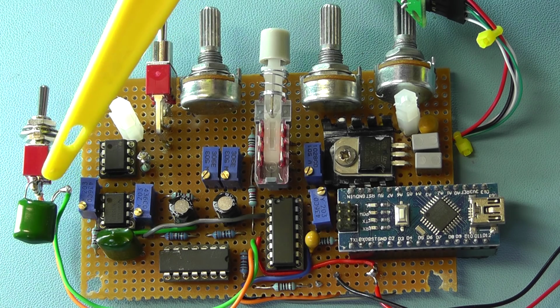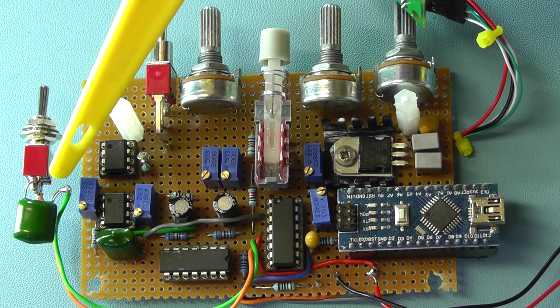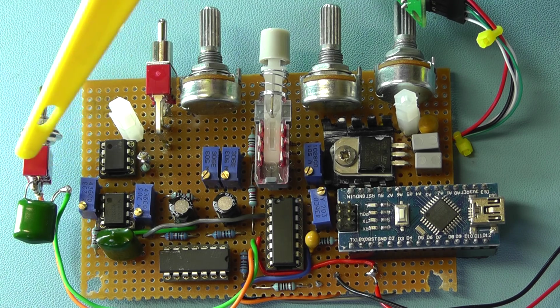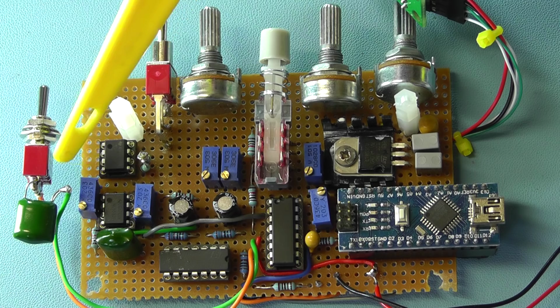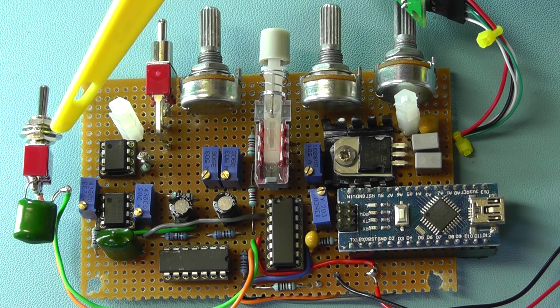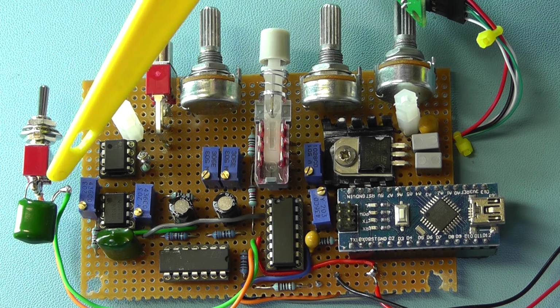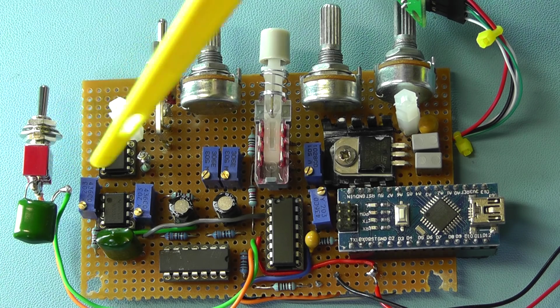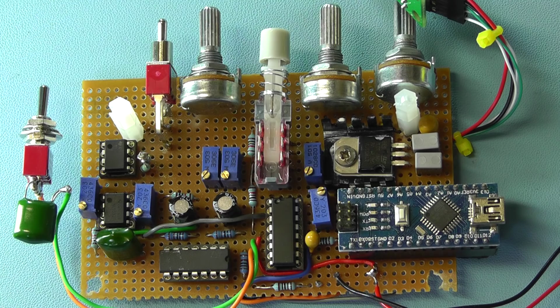That switch and the two capacitors set the frequency range you want. Remember, we had a 0.022 microfarad and a 0.22 microfarad, so we can switch between two frequency ranges. Of course, you could replace this with a rotary switch and have several different value capacitors there to give you a much wider range than what I'm doing here today.